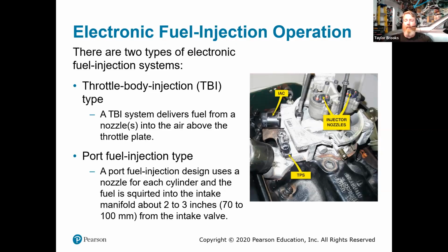However, I have found, as have many other people much more educated than I am, that throttle body injection running at higher pressure than this GM system, which runs around 30-ish psi, while I'm running close to 50 psi on my truck in a batch injector pulse, works better with a single plane intake manifold, where the intake plenum is all open and all eight ports are equally exposed and able to get flow.